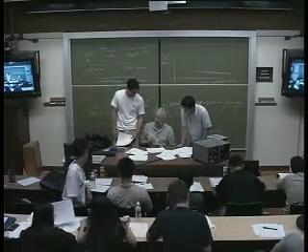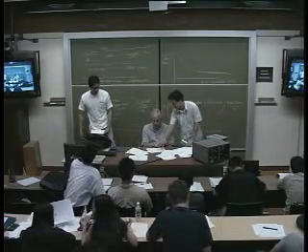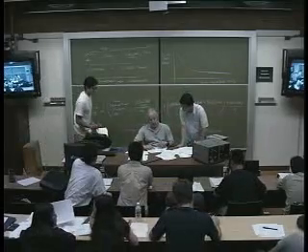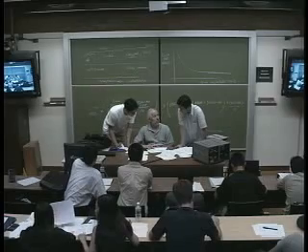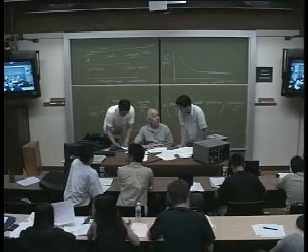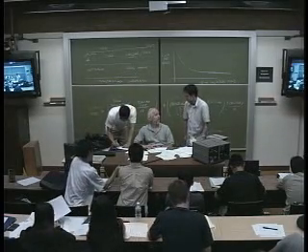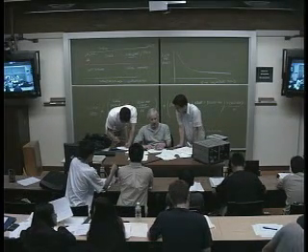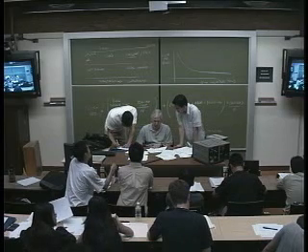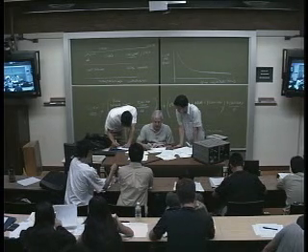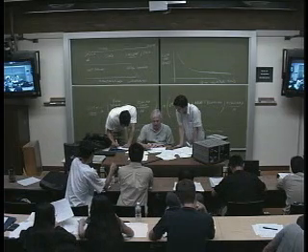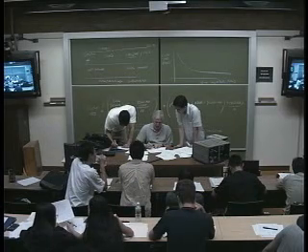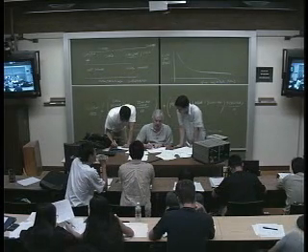Yep. Sir, can you explain again why you need to connect it like this? Let's say we didn't connect that. What's the voltage on this node? What sets it? Nothing. Well, something sets it, right? It's some little mismatch of currents. We then have to bias this up. What this actually does, you've got to look at this. It's like a diode connected transistor, right? See this, the current here equals the current there, right?